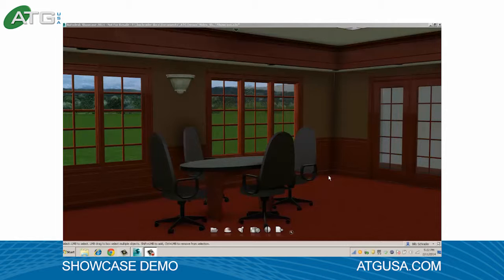We began with a Revit file, exported out to FBX, brought directly into Showcase. Once inside of Showcase, we were able to select individual faces of items or groups of items by materials. Once we had that selection, we were able to apply materials from a comprehensive catalog of library materials. Once we had those items selected, we were able to quickly switch those materials over to default materials provided in the Showcase library. Once we'd applied those materials, we were able to quickly set up design alternatives.